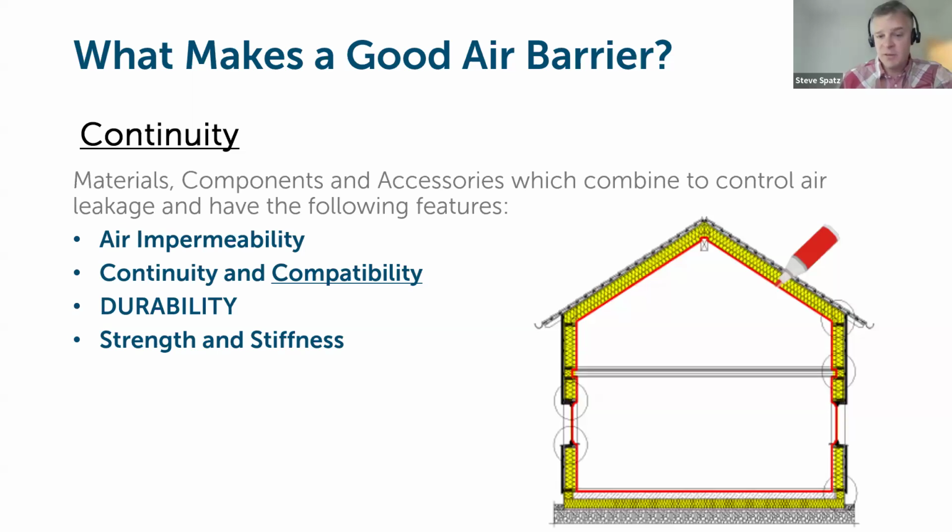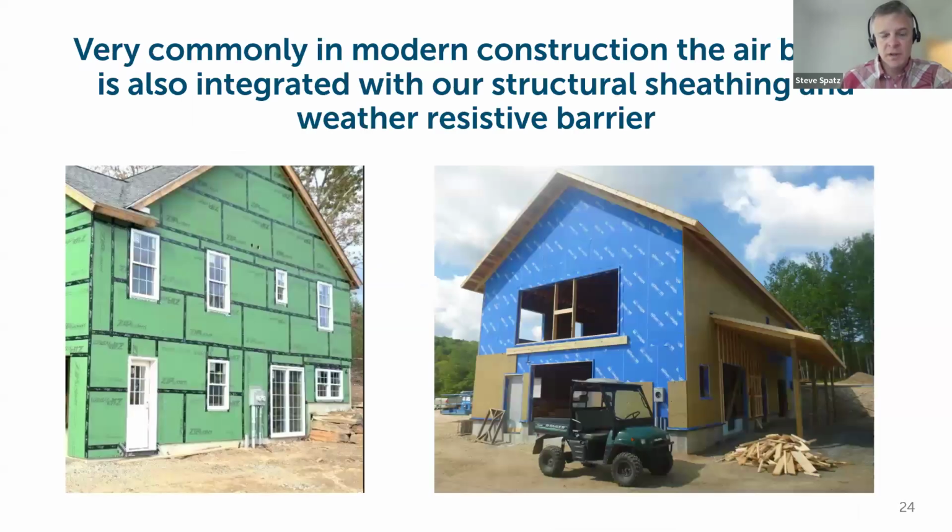And there's a variety of ways you can define an air barrier with a variety of different materials. But again, as I noted, the sheathing layer for 9 out of 10 or more buildings that we build in our climate, in our region, the sheathing layer is that durable, stiff layer in the building shell that can create an effective air barrier to the outside. You can do the air barrier in between assemblies. You can use membranes. You can use different things, but really the critical matter here is that they are compatible and durable to stand up over time.